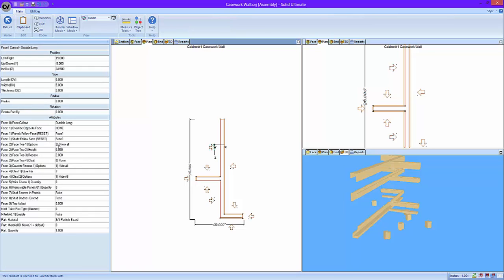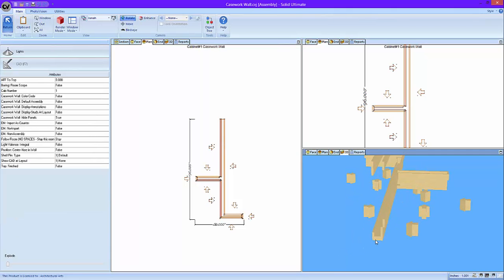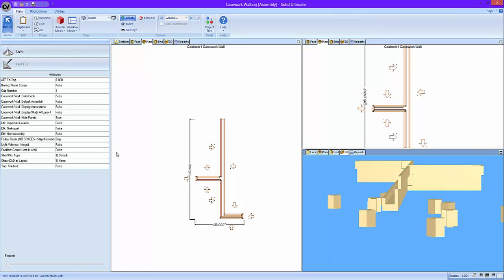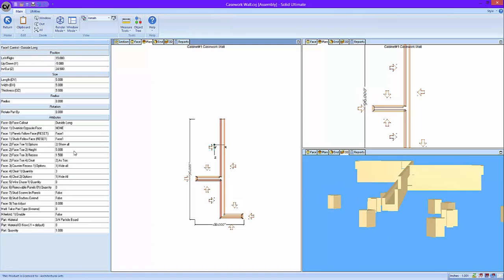And we will tell it that we want, let's just say 1.5 inch recess, and that we wanted to put a cleat there as the toe, because we just want this unfinished surface that somebody can put some vinyl over the top of. You know what? We made our toe kick 4 inches tall, not 5. And if we set behind the toe, it'll push it back behind as if we were going to put a finished panel over it.